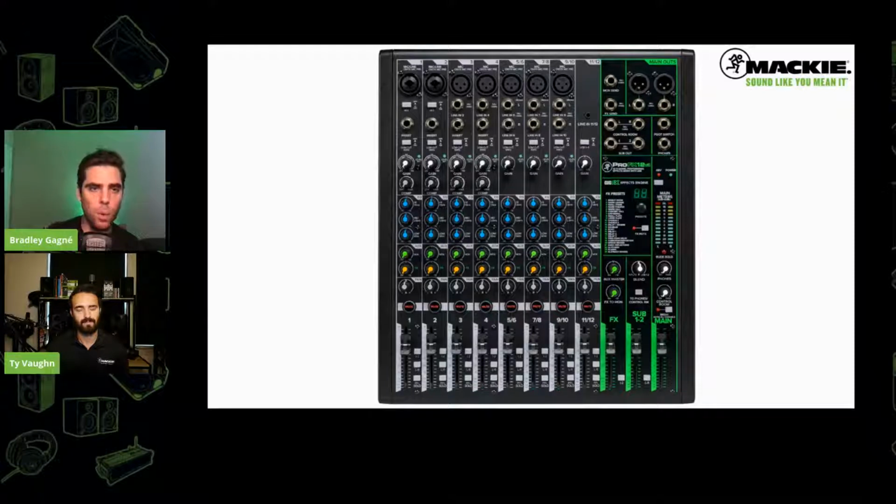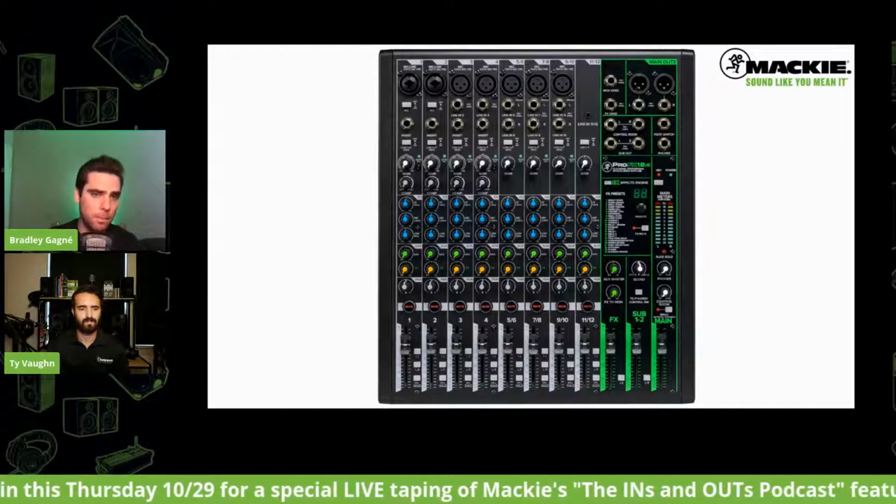I mean, you're able to plug in multiple microphones, get the audio into the computer. You can also route audio out of the computer. Like, let's say you've got your theme song, or maybe some sound effects, or some things like that. And this is what we're going to be showing you how to set up, a mix minus. So this is the setup that you would want to use when setting that up. So our ProFX V3 is an awesome live sound mixer, but like I was saying, it's also an audio interface, and it would be perfect for your podcast. Using the Mackie ProFX12 V3, I'm going to show you how to set it up as an audio interface, and we're going to go over the channel strip from top to bottom.